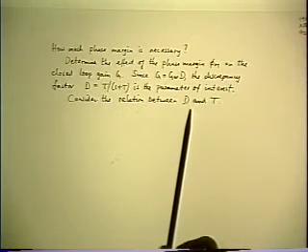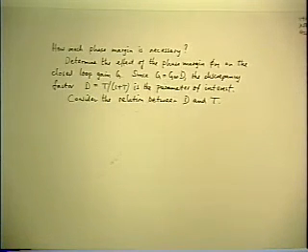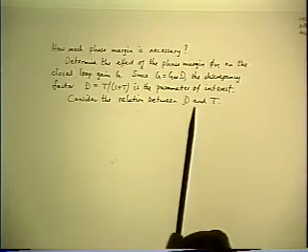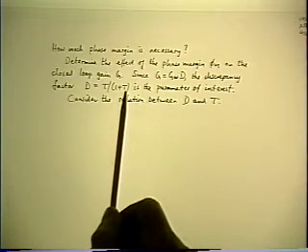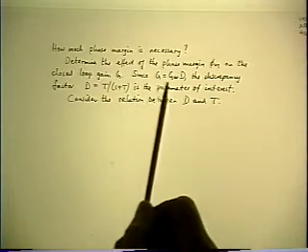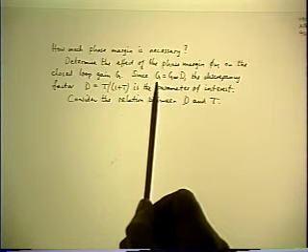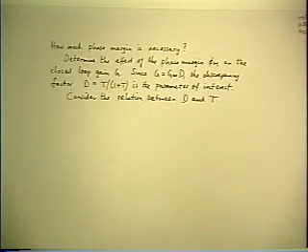So the proper question is not just, as some sort of arbitrary absolute number, how many degrees of phase margin do you need? The proper question is, what is the relationship between the phase margin of T and the shape of D, which determines the shape of the closed loop response? That's the real question to ask.